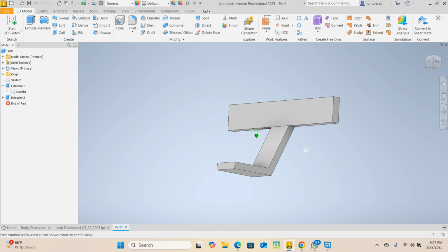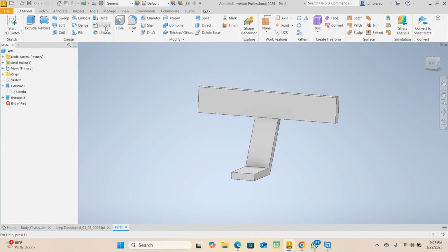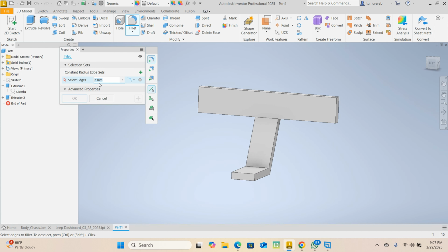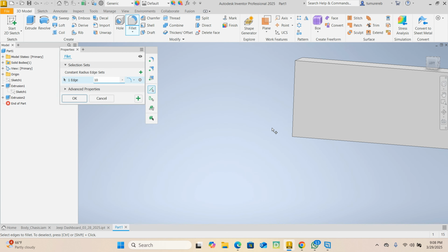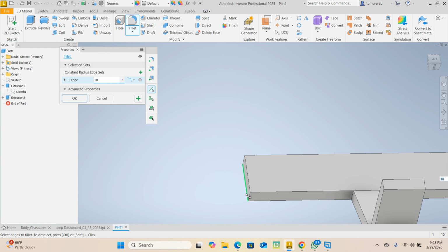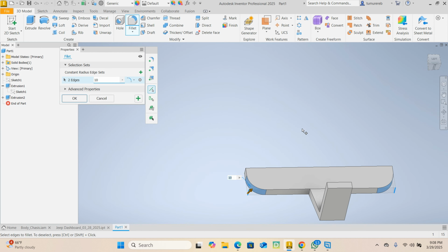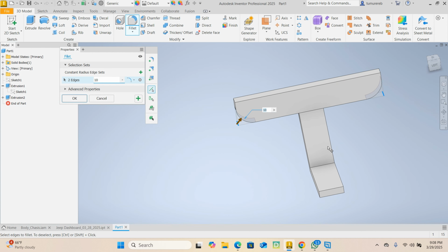Now we're going to turn off the sketch visibility, and check visibility of your sketch. Let's launch our fillet command. Fillet, and select this corner. I did a distance of 10. Radius is 10. Very good.